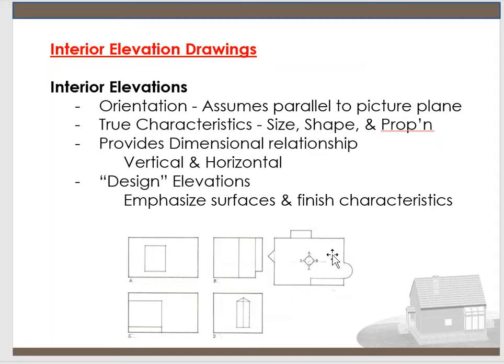And so when you're looking at a plan view, if you look at A here, they say that's A. Over here on the teeny little, what we would call kind of a diamond, they have A, B, C, D. This is called an elevation mark right here. That elevation mark represents the actual view you are looking at. So it says A, B, C, and D, and over here says A, B, C, and D. Looking at this floor plan, you would never guess that these are the elevations to this floor plan.